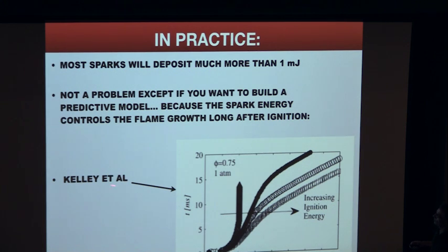That's actually another result of the Princeton group. And in Princeton, the funny thing is that they show, for example, here that when you change the ignition energy, you get different flame shapes. So that's even a problem, because the ignition phase seems to control what's happening later. It's easy to understand: if the kernel here is at 4,000 K or at 2,000 K, of course things will go much faster afterwards.